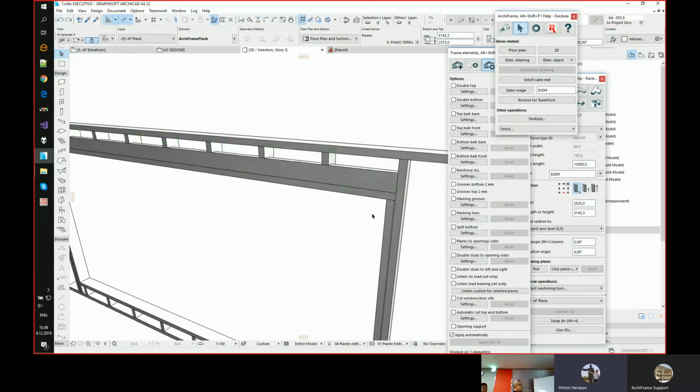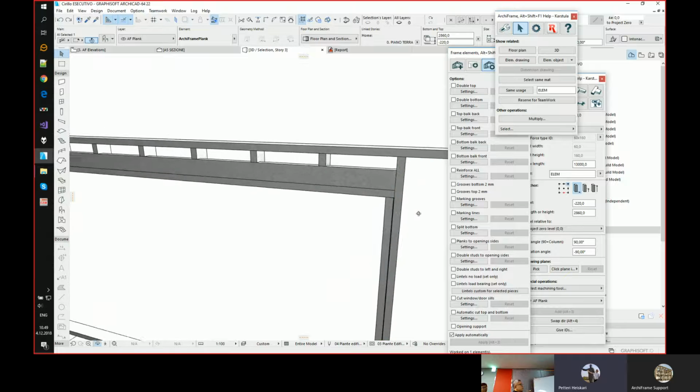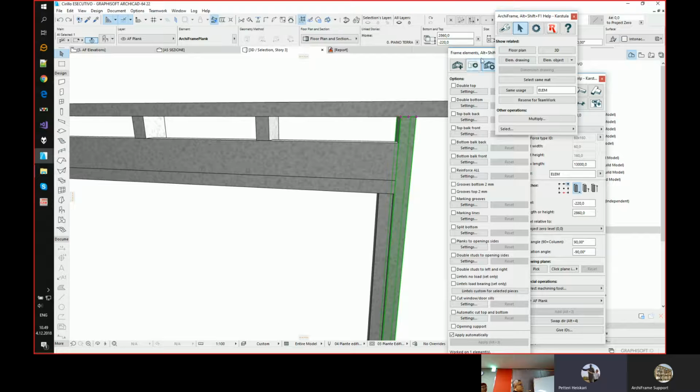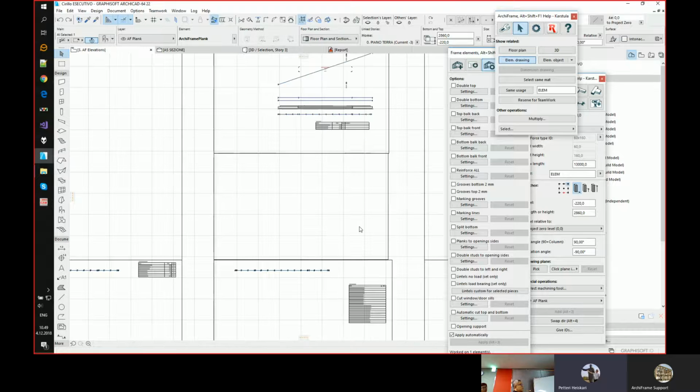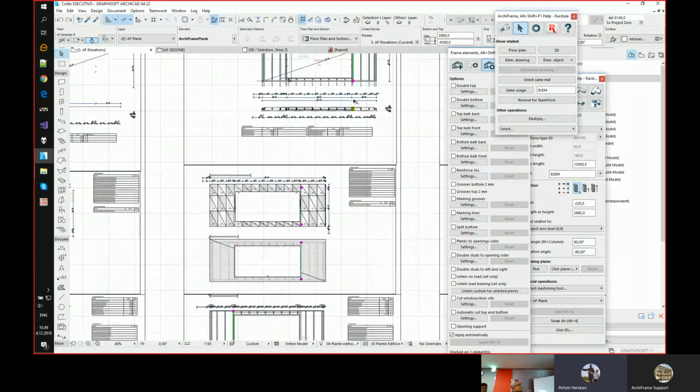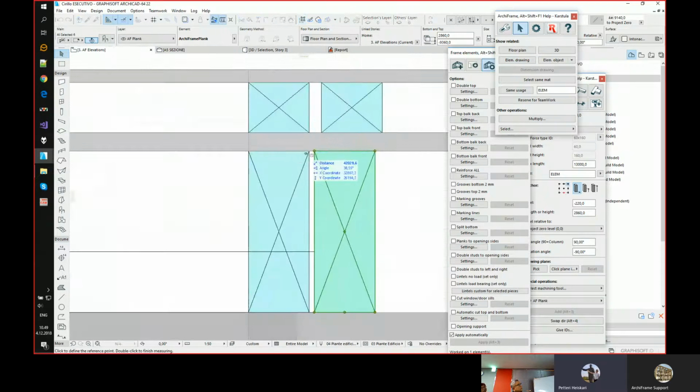And we got an additional stud here, and in our framing rules, we had a setting that the minimum distance between two studs is, I think, 5 millimeters. I selected this element drawing to see it, so we can measure from here. Yes, it is. So we have a setting that the minimum distance is 5 millimeters to be able to put some insulation between these two studs.